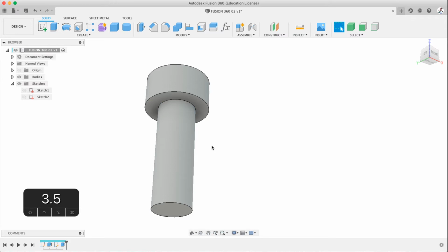change. This is something that has to become a habit for you, and it's really important, especially when you have very complicated objects with very, very specific references, because you don't want to have to go back and change a million different things that have the exact same sizing within an object. Let's say you're making a head gasket for a car, right? You're going to have the cylinder sizes, you're going to have the bolt sizes. Well, why wouldn't you just make a parameter for bolt sizes and cylinder sizes? And that way, if you have to adjust it for a new version of the engine, then you can actually just change the cylinder size by whatever size it is, and all the cylinders will change.